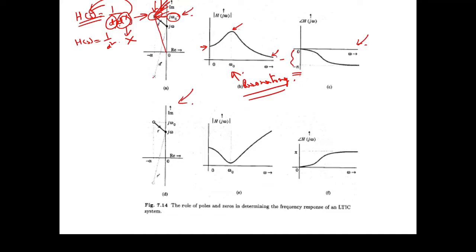Similar logic to what we applied in the single pole filter will be applied over here. We have R, so H(s) will depend on R. The larger the distance, at 0 there is a large distance, we have some particular value, and as we go down and up towards j omega naught, the distance is reducing.